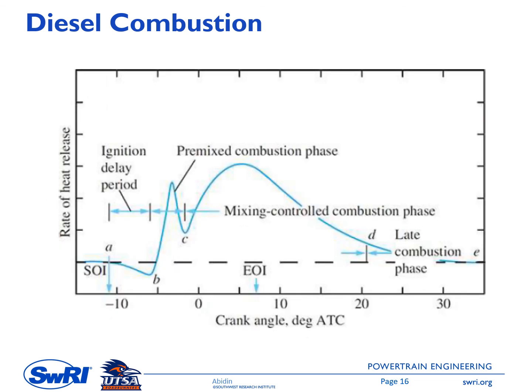Okay, so this is a more detailed explanation of the heat release rate for diesel combustion. Let's start with point A here. This is where the diesel is injected, so it's called start of injection, or SOI. Then point B here is where we have the start of combustion, SOC.